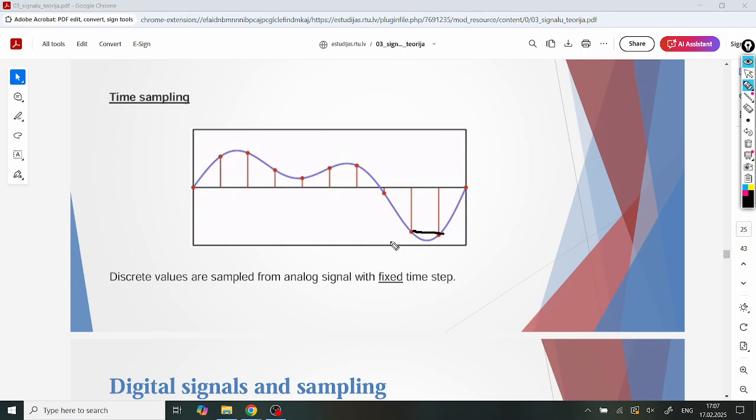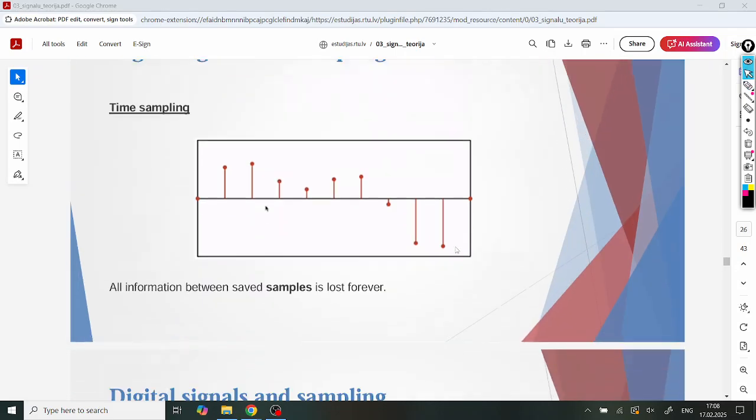Yes? So the original signal was going like this curved shape. It decreased, then increased, and decreased, and started increasing, and it was not monotone at all. Now, if you just connect with a straight line, your signal is going to be not so accurate as before. Now, you may object that we just need to read more samples, then our line is going to approach this line. True, but also unnecessary, because we are going to connect these points with a different approach.